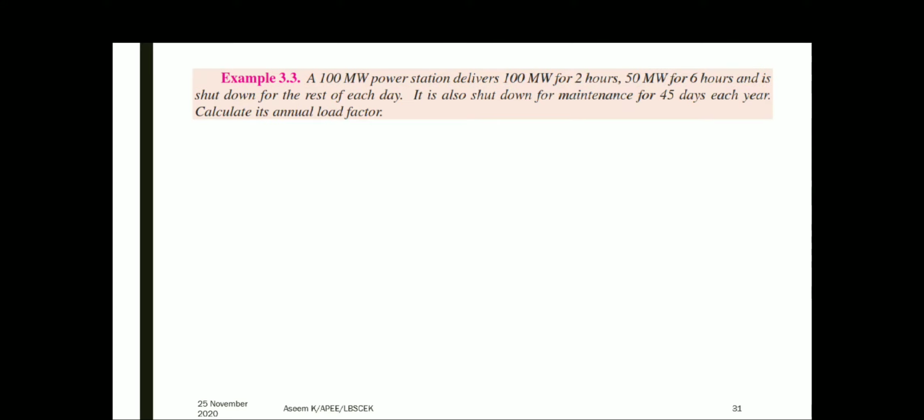And in this example, a 100 megawatt power station delivers 100 megawatt for 2 hours and 50 megawatt for 6 hours, and it is shut down for the rest of each day. It is also shut down for maintenance for 45 days each year. Calculate its annual load factor.